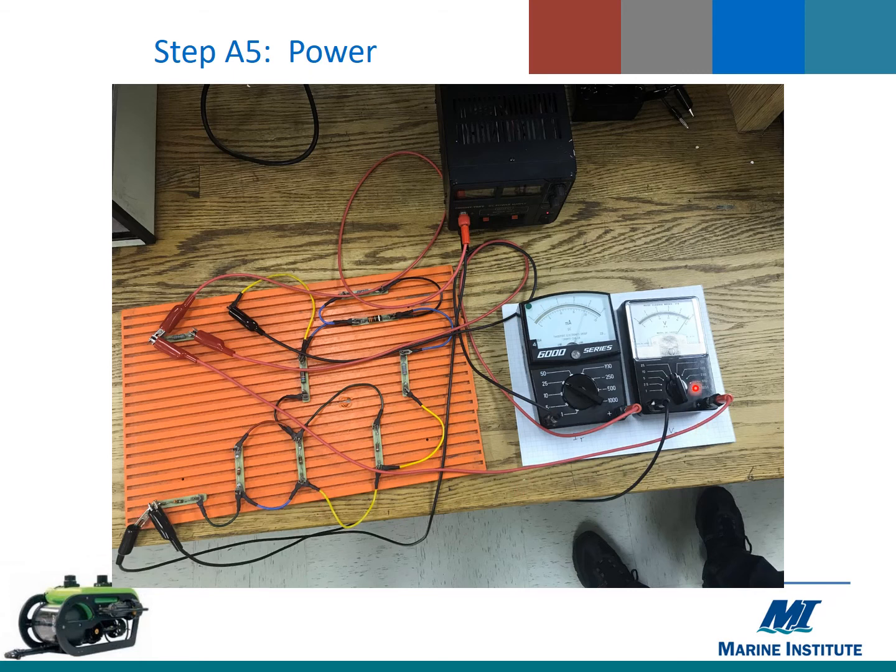Now, our voltmeter is here, and we have connected the positive terminal of the voltmeter to the positive terminal of the circuit or the source. The negative terminal of the voltmeter is connected through this black wire here, and even though it goes under the table, it comes back up to the circuit here. So it is across the circuit, so it will measure VT.